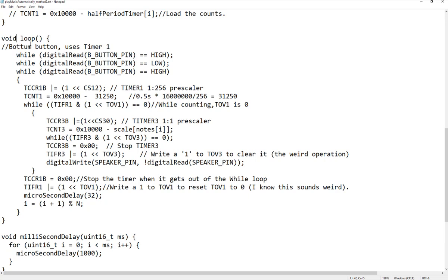And temperature sensors, a lot of people will think about that. Probably the first thing that came to their mind. It can detect the temperature, but the thing is, it's still hot, right? You can do a little math on the microcontroller. Just get the temperature change, get a derivative over time and see if the temperature is decreasing rapidly, so you know it's turned off. But still, you need to wait. There's still a delta T over there, right? And I have thought of so many different ways.